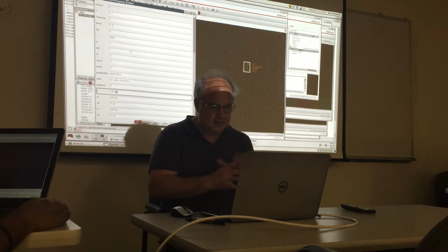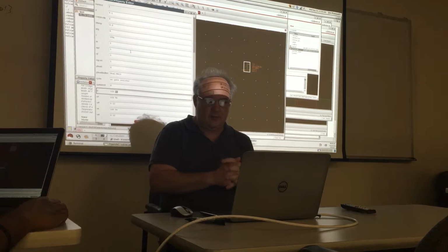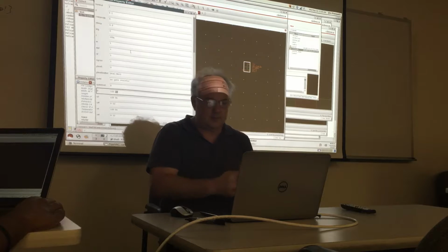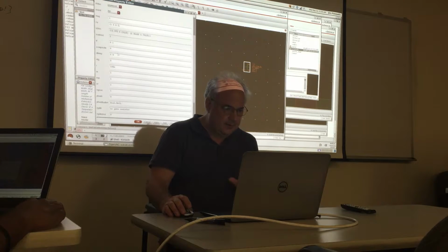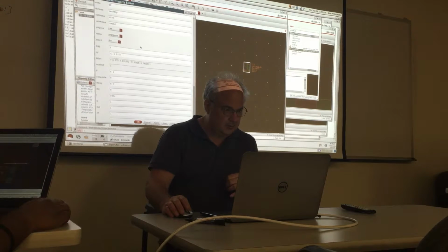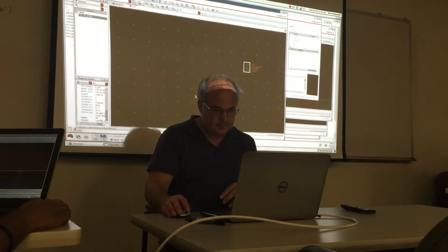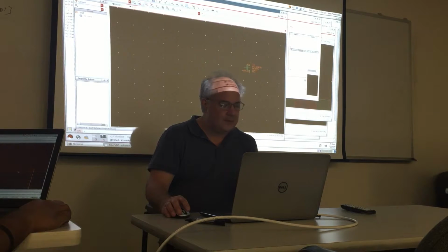Just make the device, and if you have to create like a wrap in your layout, don't worry about it. Always keep one finger here. So the only thing you'll change here, my point is, is the width for the most part. Yeah, pretty much. And we just make them match the size of the transistors you have in the layout for the inverters.